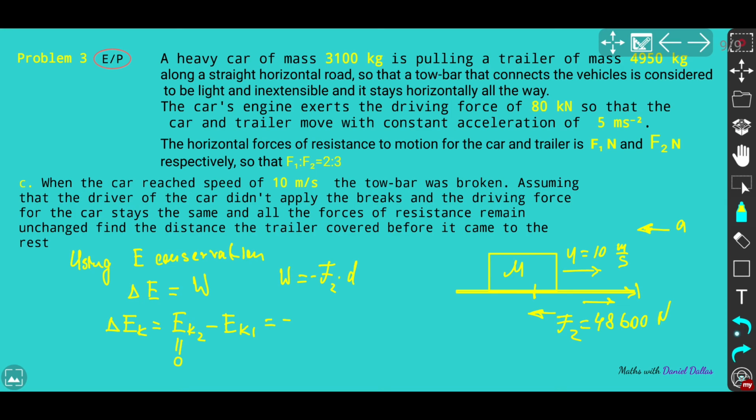And if we equate that to the right side, we'll get Mu squared over 2 is going to be equal to F2 d. Now you understand why the two signs, we actually need them, because later on they will cancel and everything is correct. From where we can express distance. So distance from here is going to be equal to Mu squared over 2F2. So you understand that I actually put more effort, and that's why it took a bit longer, because I explained in detail how to apply this.